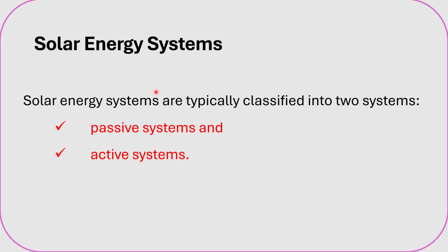Moving on to the active solar systems, they typically involve electrical and mechanical components such as tracking mechanisms, pumps, and fans to capture sunlight and process it into usable forms such as heating, lighting, and electricity. The panels are oriented to maximize exposure to the sun. Depending on the system, the panels will then convert sunlight into electricity, which is then converted from DC to AC form and stored in batteries or fed into the local utility grid. Active systems are more expensive and complex.